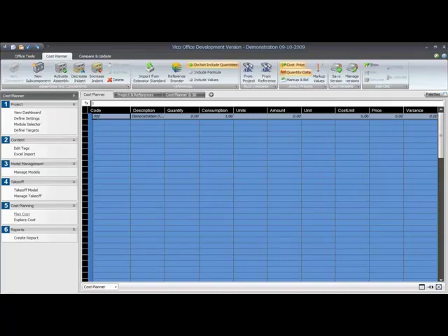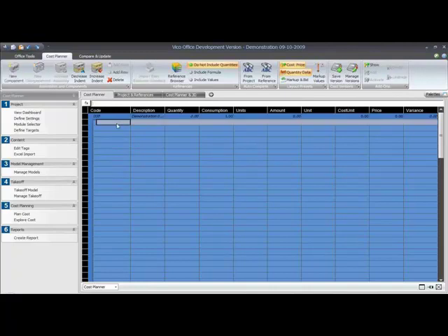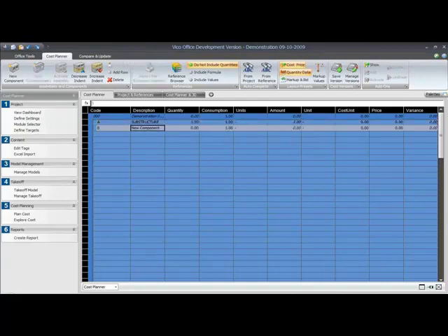Initially, this section is empty. We only have one line item, and that's the project level, and that level is going to be used as the summary level for all of the cost in the project. So what I want to do is first put in 3 cost allocations for the substructure, for the shell, and for the roof. Actually, I want to make that for the walls and the slabs to make it possible to use the current set of takeoff items.